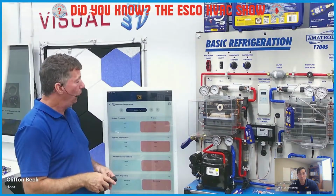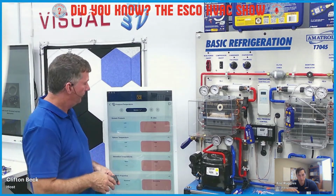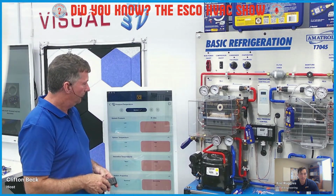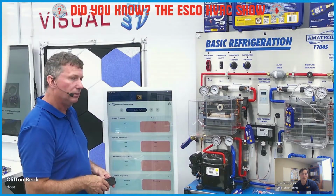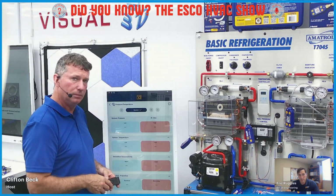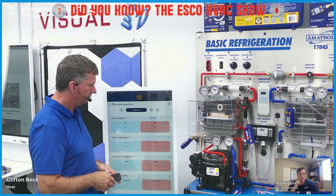Oh. So you can connect another set of sensors, and then you can swipe back and relabel those Unit 1 or RTU1, RTU2, or whatever you're doing. You can do up to 4 sessions at the same time. Same with the psychrometer session when we move over to that. So it allows you to work with multiple sessions if you have multiple sensors, or you have a Titan Max or other digital manifold hooked up, and the sensors on the other unit, you can do multiple units at a time, which is kind of cool.